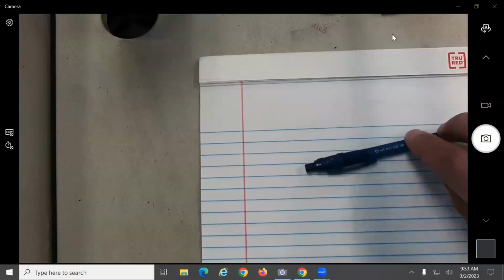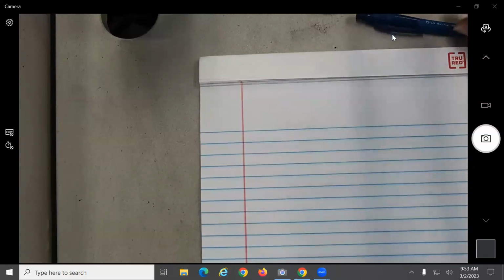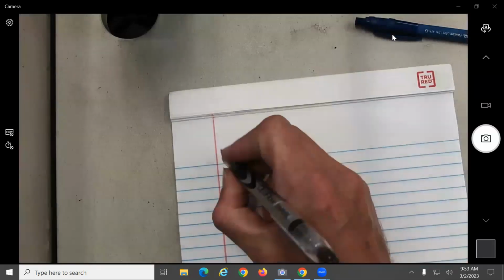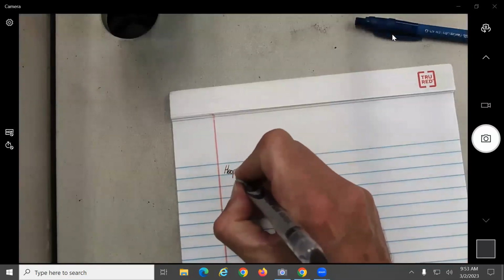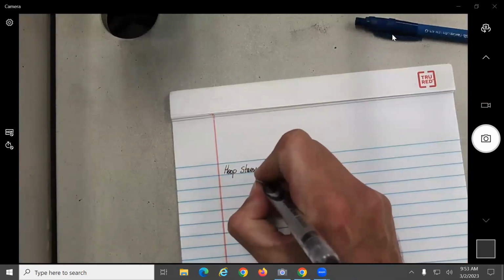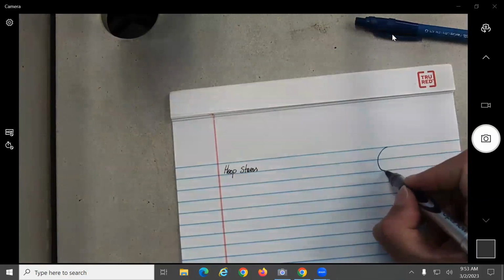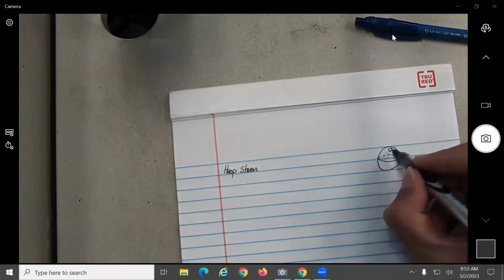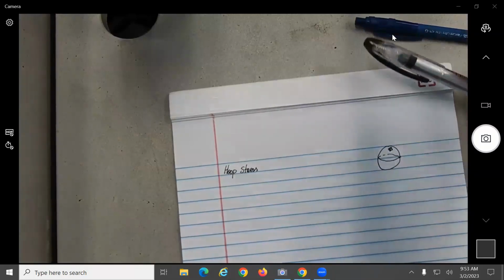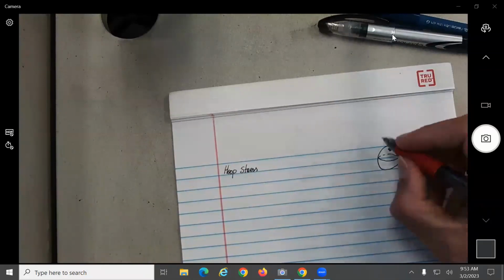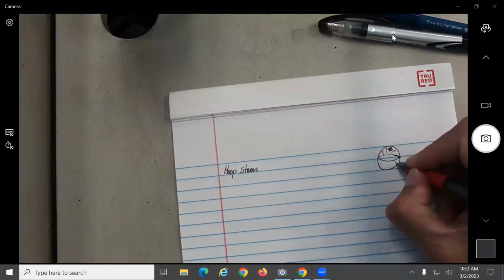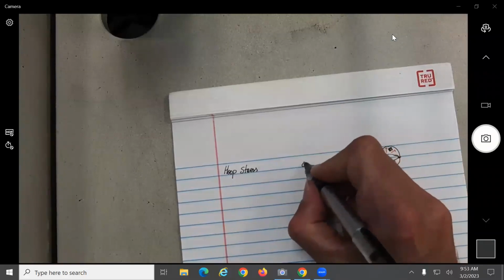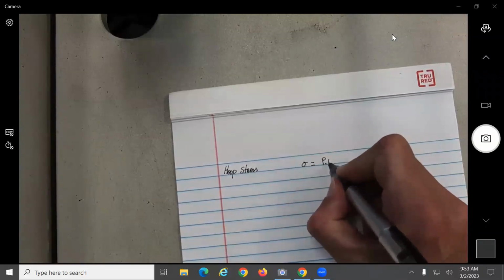Okay, so in today's lecture, we're going to do some examples about the membrane stress and the hoop stress. So maybe we can remember this equation. So basically we have the hoop stress. If we have something cylindrical, what will be the value of the stress in one little element over here? Probably need to figure that the hoop stress will be the same independently of the direction. And I think here you have sigma equal, what is it, PR?